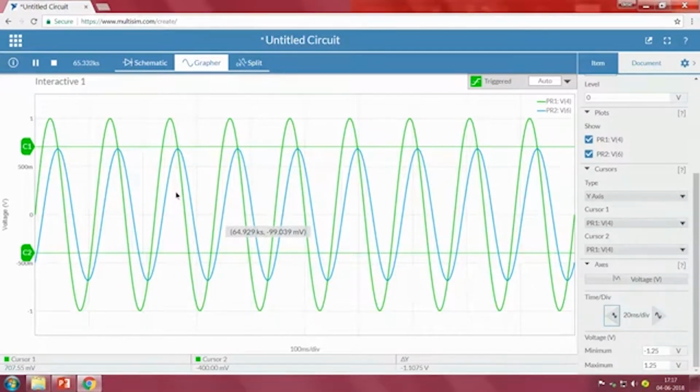If not, try to set our op amp resistor to one particular value and change our resistance values. But if we are really interested in a narrow band of frequencies, one good way is changing the resistance value, and we can observe that there was this drastic change from 44 hertz to 45 hertz itself, and below that particular value it will be completely below the cutoff.